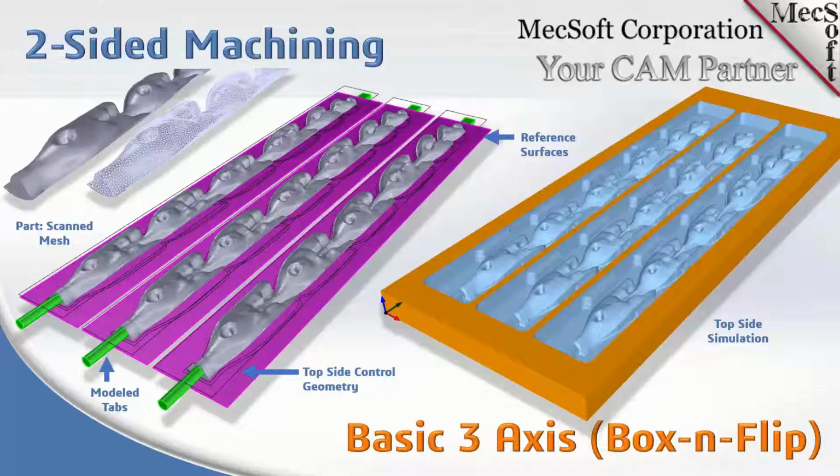So instead of the tool retracting over and over, just put a surface under there for the tool to land on. That surface just needs to be at the Z location to make sure it encompasses the entire part from one side, and the tool will land on that. As you can see in the simulation on the right, the rectangular plane is where the tool stopped, and it machined all of the part with the tabs on each of the ends. And then this is flipped over.